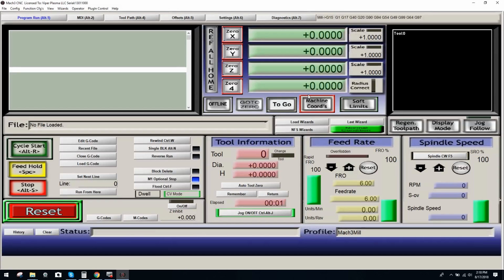Okay? When you click it off, if you are in your default offset, which is the offset you will find when you enter Mach 3, or should find, you are in G54. So your default Mach 3 offset is G54. Please write that down. Okay. Once you've written that down, and you know that when this machine coordinate button is off and you've just